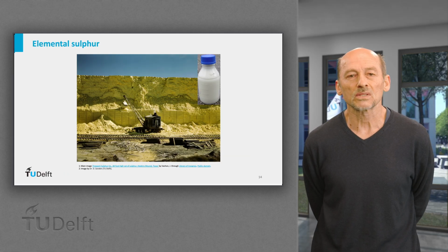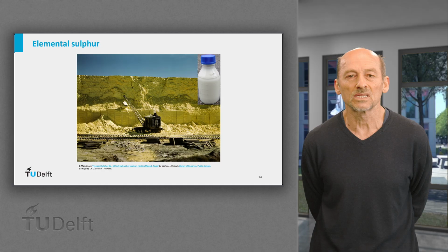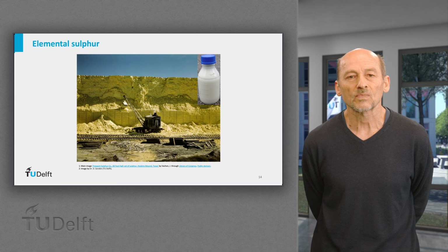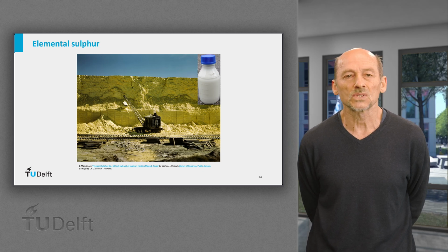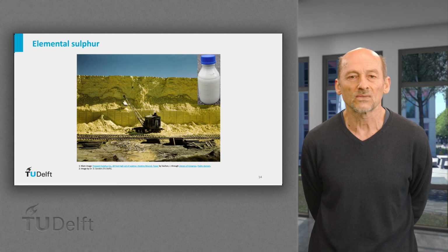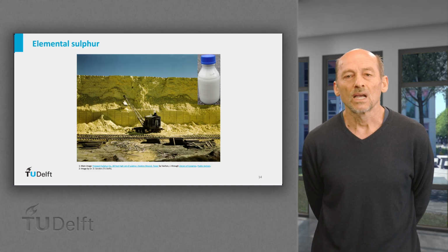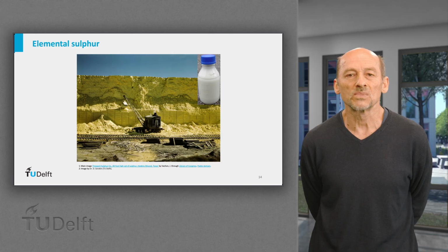Hydrophilic biosulfur produced in the THIOPAQ units is very different in its physical properties from the naturally occurring volcanic sulfur ores or sulfur produced in chemical desulfurizing technologies. This slide shows examples of those two forms of sulfur, the native hydrophobic orthorhombic crystalline sulfur mineral and hydrophilic amorphous biosulfur produced in the THIOPAQ bioreactors.